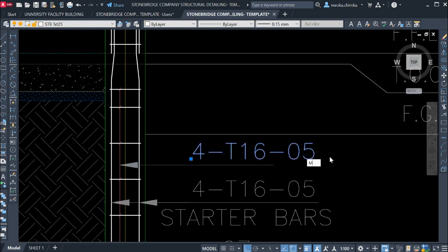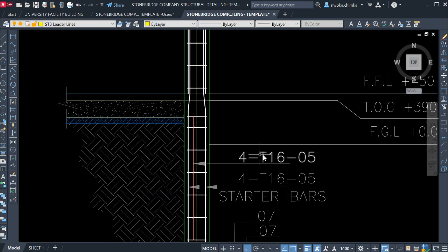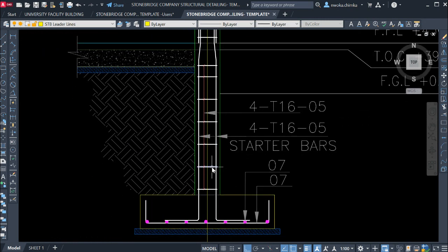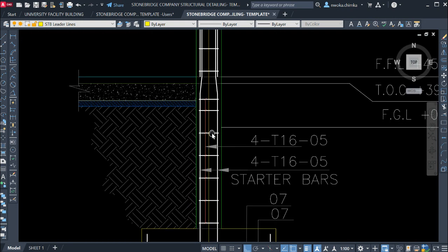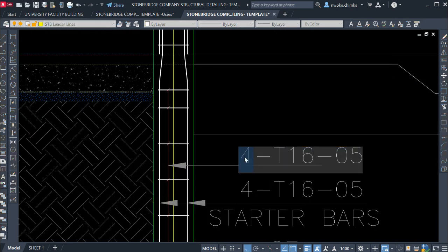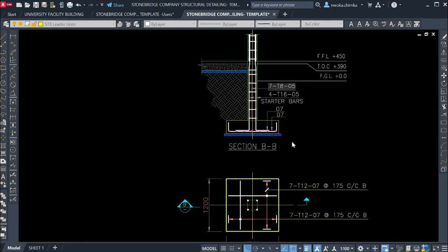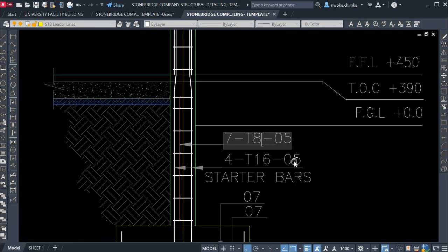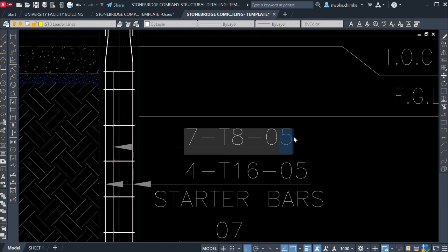So go and bring them downward again, and then show the number: we have 1 2 3 4 5 6 7. So we have 7 links for that beam at diameter 8. You can see that. Now the bar mark, we already have 7 7 and 5, so I'll put this into bar mark 6.